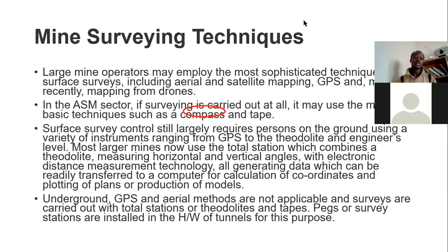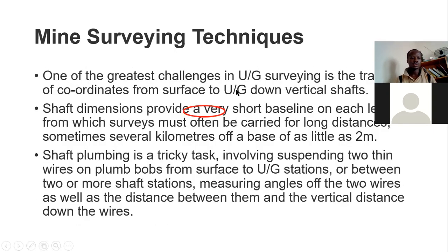So we should take note of the fact that satellite methods, GPS, use satellites. It won't work underground. So you go in there with your total station, switch it on, make sure you have battery, and you start turning angles. And you'll be good to go.